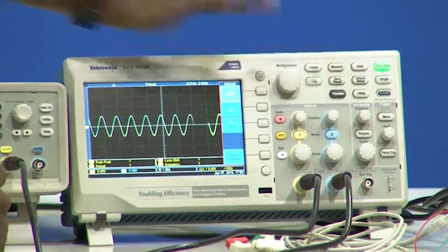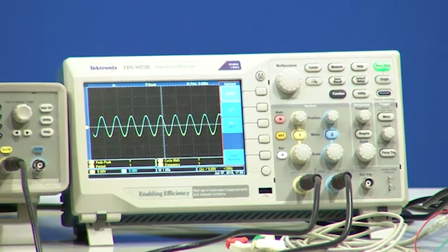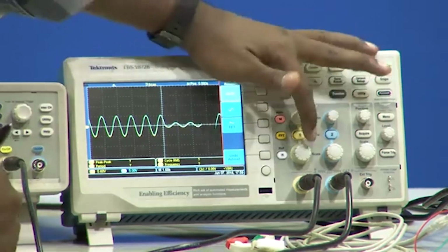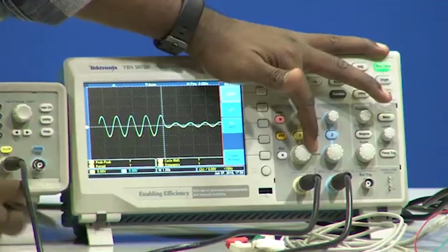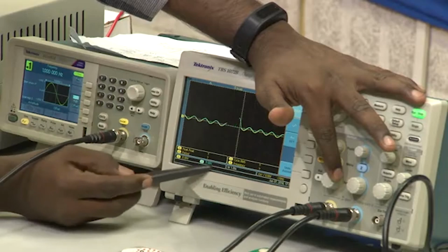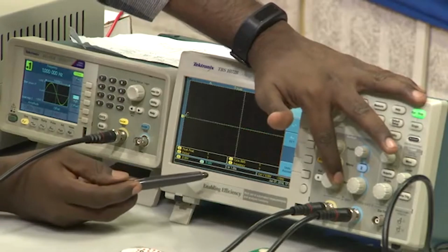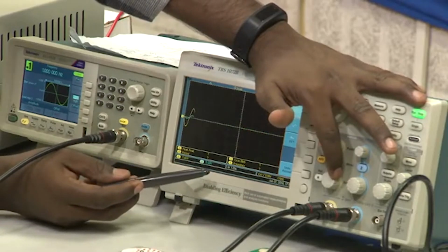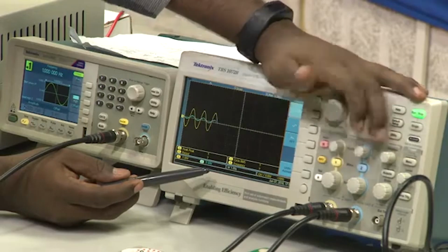5 volts. So, let me change my amplitude to 1 volt. I am setting the amplitude to 2 volts peak to peak, so that is nothing but 1 volt peak. Now, I will zoom this particular. If you see, one box in this case represents 5 volts, right. Even in this case one box represents 5 volts. So, let me change one box to 1 volt, and even here.